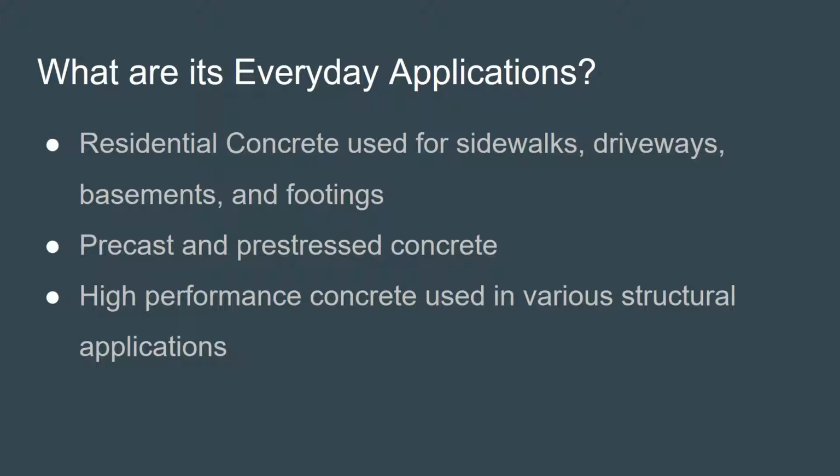There are various applications for steel slag cement. Each depends on the specific slag and mechanical properties. Some uses include highway construction or structural applications. Slag cement can be used widely in residential concrete applications, which is becoming increasingly more popular for aesthetic reasons. Steel slag cement is used for footings, sidewalks, driveways, and even some structural uses in the houses themselves. The reason for incorporating slag into these cement mixtures is to lower the cost and increase energy efficiency.